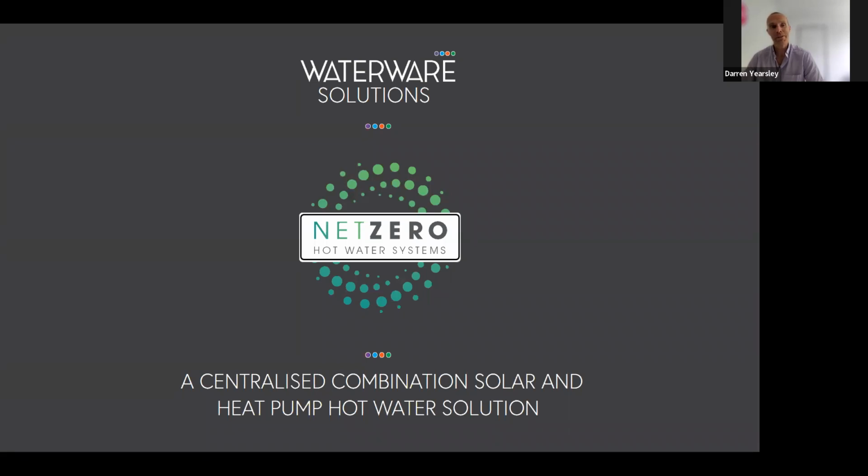So one of the advantages of this multi-unit accommodation, and also for business, is we can phase our system so that we use that hot water when the sun is shining. And that's why it fits so well together when you've got these two peak periods of, I use a lot of water in the morning, I can recover it during the middle of the day when the sun's shining, and then I've got a smaller peak period in the evening, which I can coast through.